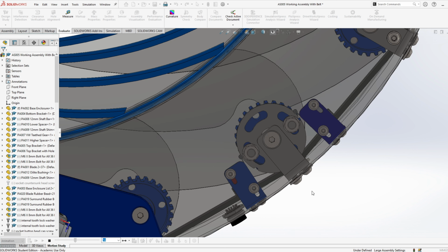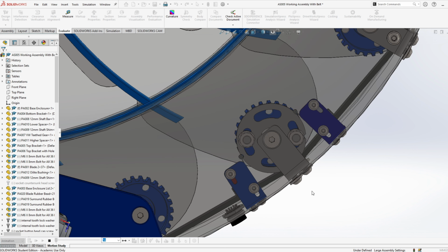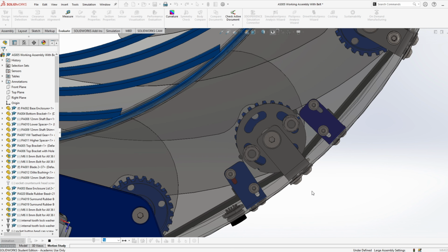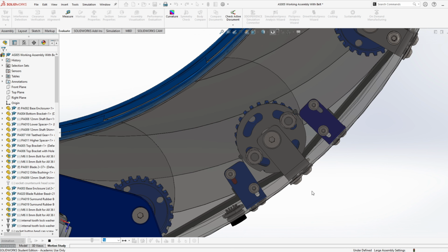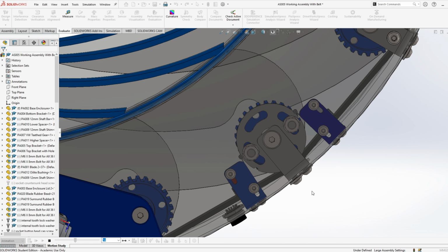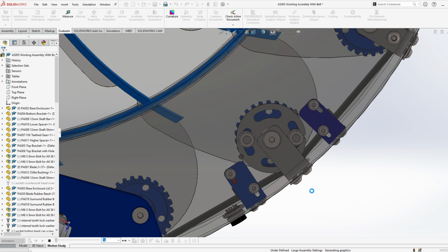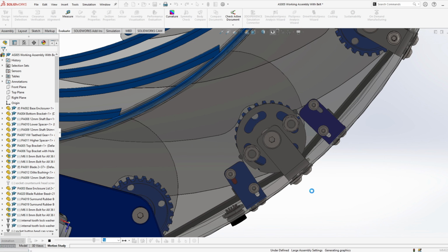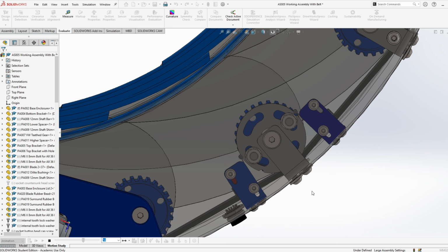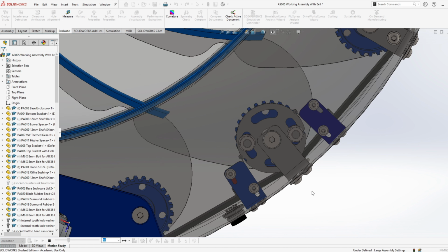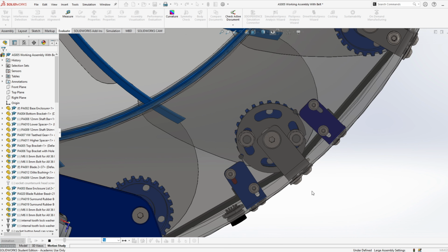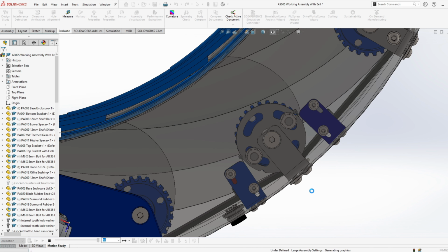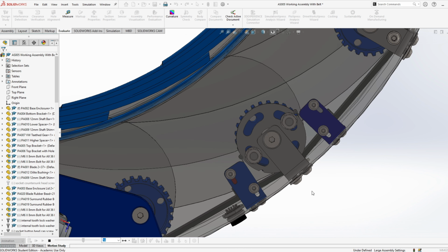So 2 additional brackets were added to the enclosure seen at this new detector Aperture positioning plate to attach the new opening and closing limit switches to the left and right of it here. As seen with these brackets, these switches can be adjusted to set the Aperture's maximum and minimum open and close states by moving the switches on the slotted holes. In other words, altering the angle of orientation spoken about, increasing or decreasing the 46 degrees range of the diaphragm.